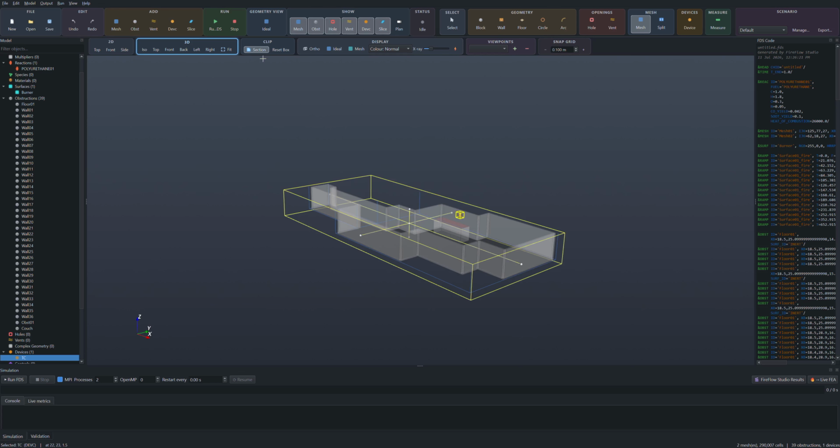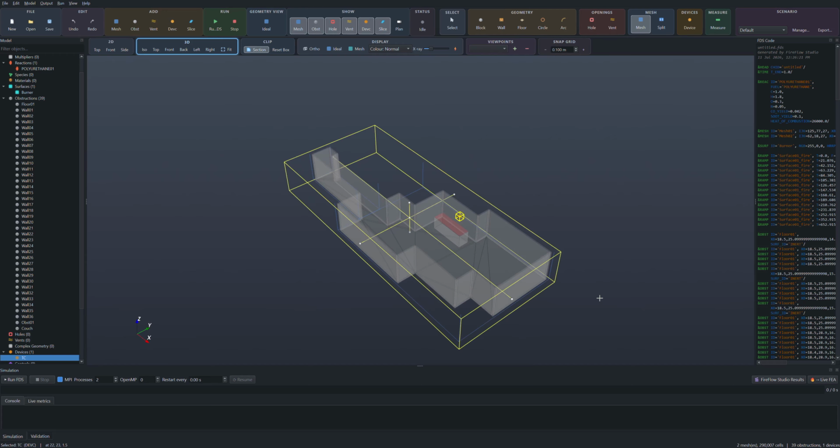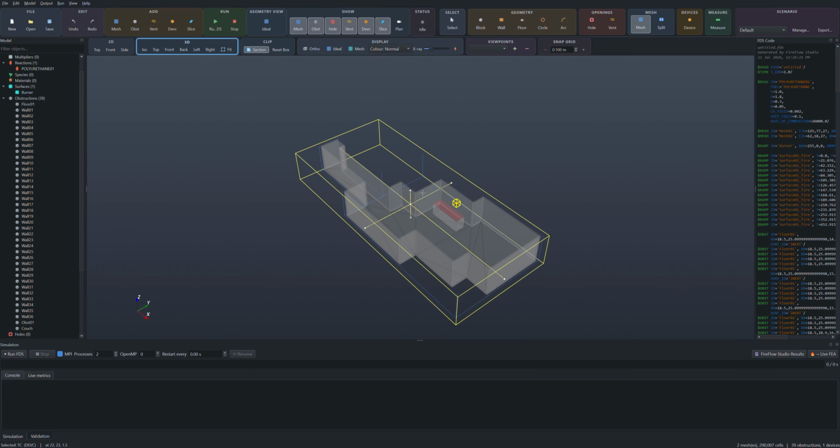And if I then take a section box down, the next feature I want to show you is the ability to model both gas phase and solid phase within a single application, right? So all of that gets modeled within the software. It's absolutely fantastic. But to enable that, we need to set our boundary conditions as AST, adiabatic surface temperatures. We have to activate that so that we have a boundary condition to feed into our finite element model.